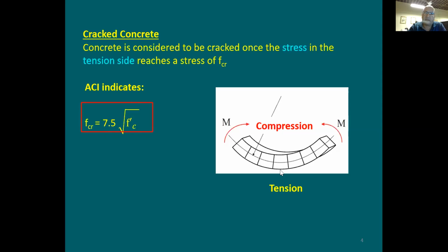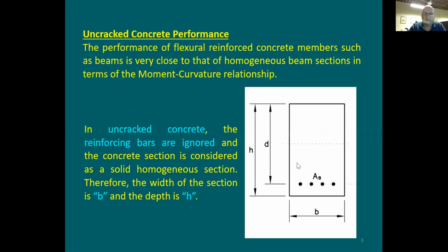The bottom of the beam is going to crack, and the beam depth itself is going to shrink. Let me take you back one slide. Just imagine, at the bottom, the crack is going to happen. So what happens to the total depth? It's going to get smaller because the concrete here is not going to be good. If the concrete cracks in tension, it means it is not effective anymore. So the beam depth is going to get smaller.